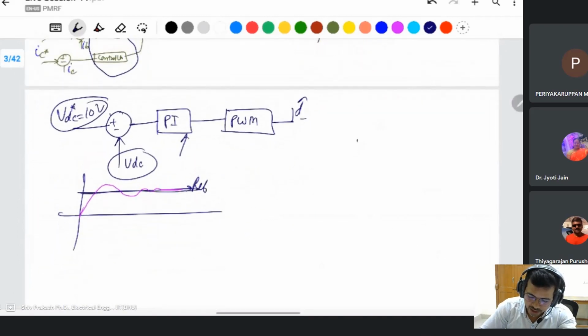If you have a constant signal like this, then you can use any controller, like a PI controller, on that signal, because your reference signal will be constant. The whole three phase AC system will be converted into a two phase DC system, equivalent to the DC system, known as the DQ transformation,